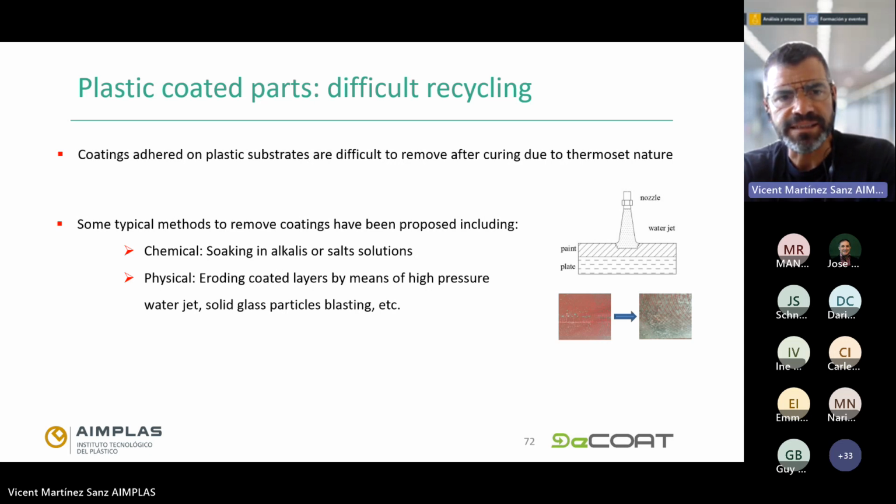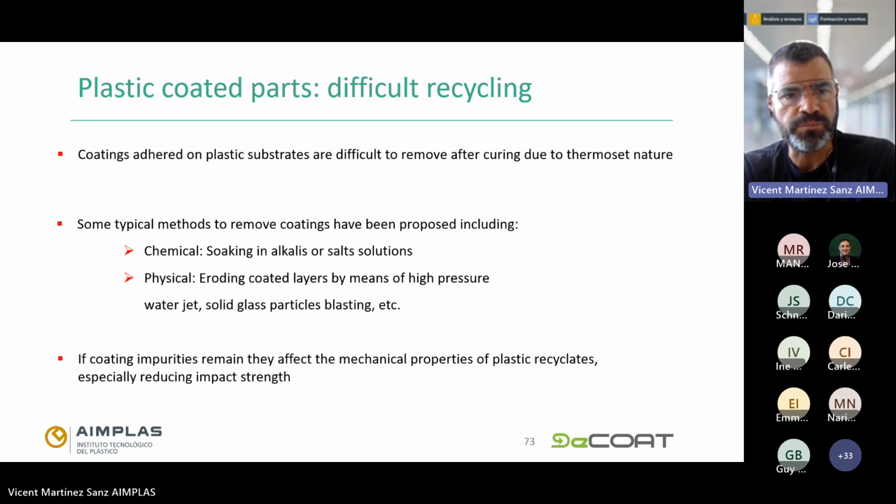But these methods, generally speaking, have shown low effectiveness, especially when implemented at industrial levels, and also consider that if some coating impurities remain after these erosion methods, they can affect the mechanical performance of the plastic recyclates, especially reducing the impact strength.